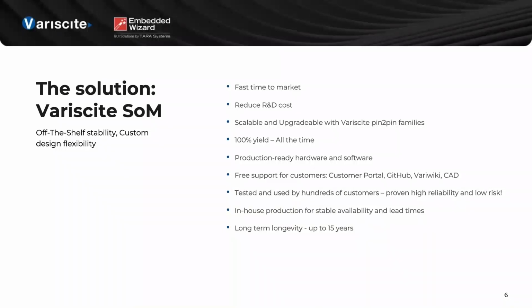The advantage of using a SOM solution is to quickly reach the market, because you start from already tested hardware and software. You will experience reduced R&D cost because most of the software and the hardware is already pre-tested. So you just need to take care of the carrier and customize it according to your needs. You have full scalability and upgradability because of the pin-to-pin families. Variscite, as we will see in the next slides, provides a series of families that allow you to use the same carrier board with different SOMs. 100% yield all the time. All the hardware and software is production ready.